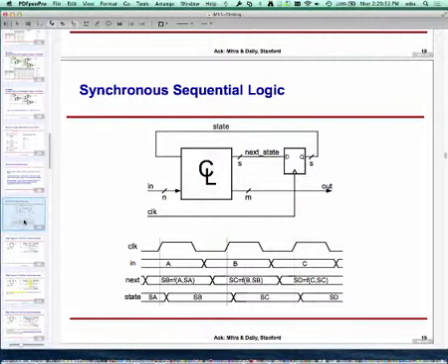So now imagine I have my sequential logic. I have combinational logic, and flip-flops which constitute my state register. Remember, the way this system works is that at every clock tick, potentially a new value comes into the state register. After a little bit of a delay through the flip-flop, which would be the propagation delay of the flip-flop, I will get a stable new value for the state. So the current state has now changed to a new value. This will go through the combinational logic, and then after some time, the next state will become stable at its new value.